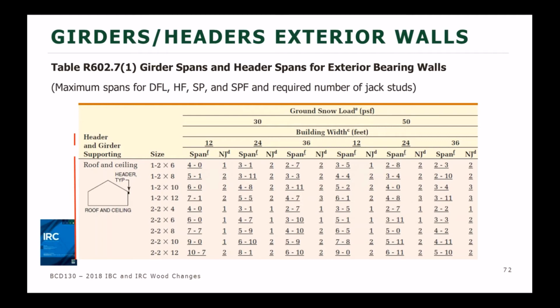So multiply that 0.7 factor to each span length and reduce it to a shorter span. So there will be reduction in header lengths again, and perhaps that will drive at least the longer spans to using a manufactured lumber similar to what we already see at the front of garages. So you may see more LVLs occurring in some places.